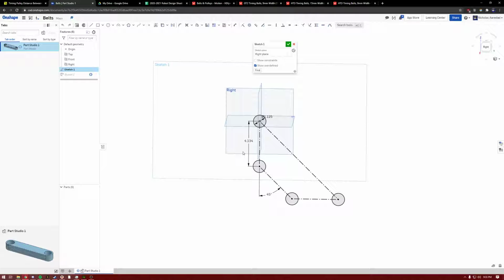That's not always 100% true, right? There are cases where you want to go over the dead center to center, and cases where you want to go under the dead center to center. So let's talk a little bit about when you would want to go over. I might want to increase this by a very small amount if I wanted to put more tension on the belt, which would help reduce some backlash and some belt-induced skipping.